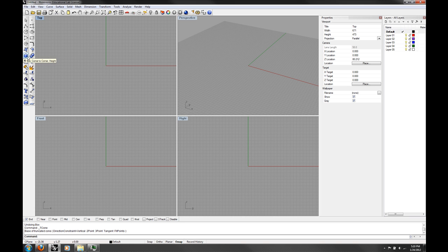So again, icons are one way to make things. Another way that's very familiar, it should be familiar to us in CAD, is to actually type in what you want. So you can start typing in, box. And as you type, as you can see, I start typing B. It's going to give me a list of commands that it thinks I want, and then I can choose one I want, right? And just like in AutoCAD, it has